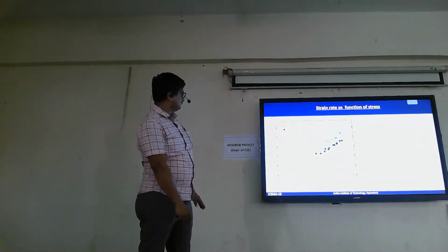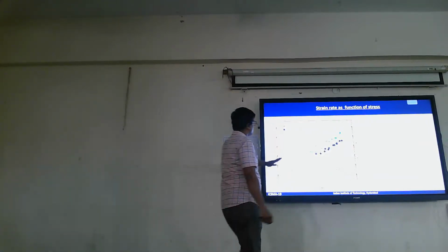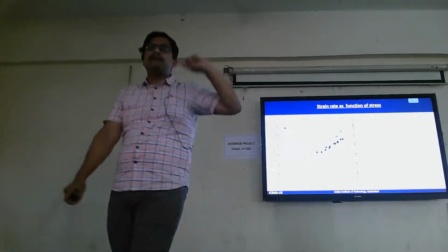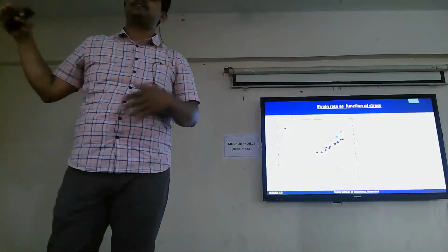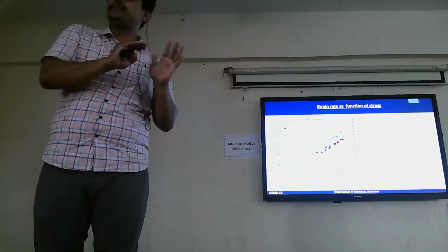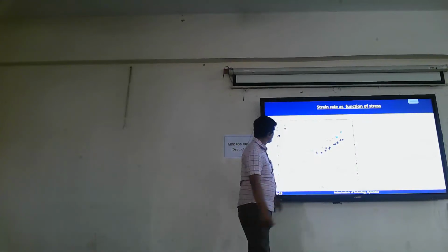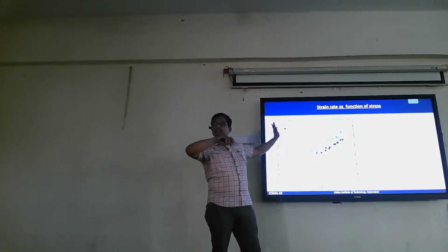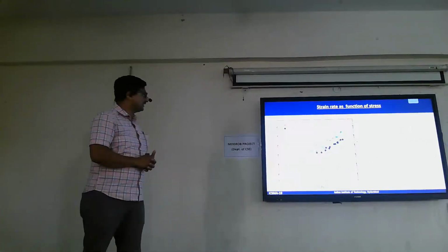Then, okay, that graph is gone. Now the graph which was missing actually shows that the creep rate of this alloy is two orders of magnitude lower than the creep rate of conventional high temperature alloys of this class, which clearly shows that these materials have very good creep resistance compared to the present conventional materials at this temperature. So now we plotted the creep rate, that is the strain rate, the slope of the creep curve in the steady state region, against stress. If you don't understand, don't worry.